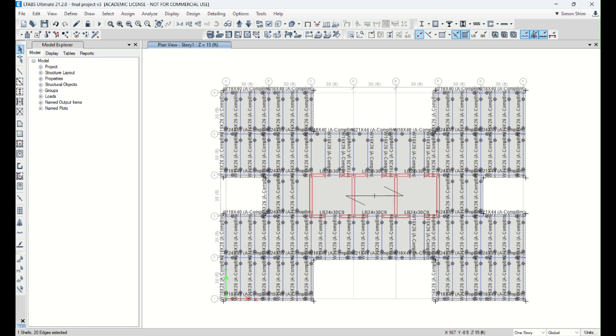I've been told that a typical 40 to 45 feet is pretty common too. But since you have a geometry well set at 30, it's okay, right? No issue. So now you choose all the beams to span in this direction, right? So the plate you draw, that one big plate, spans in this direction, and it should be all perpendicular to your series of beams. If you happen to draw it in this orientation, it's totally wrong, right? It's going to fall down, right?